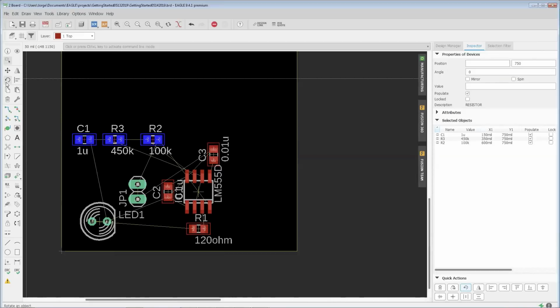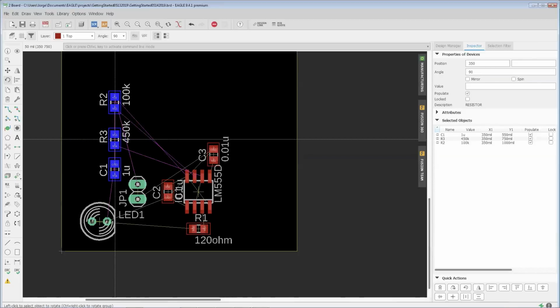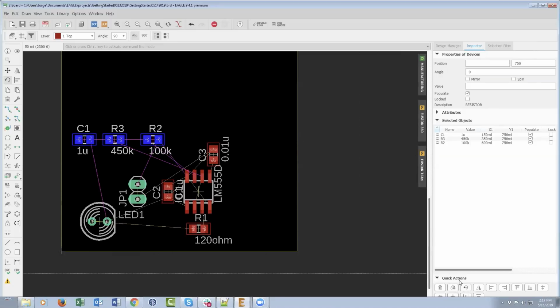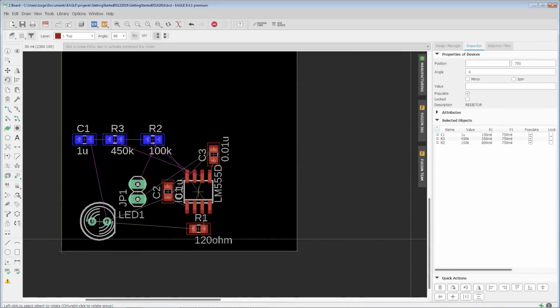So let's highlight that using the rotate command here, set to 90-degree increments. If I control right click to apply the operation to the group immediately, you'll see that it all moves like that, but they don't really rotate in place like they can now with the inspector. So that's a new functionality for those of you who need that. Brand new functionality with the rotate command.